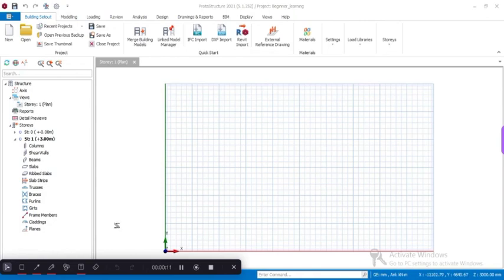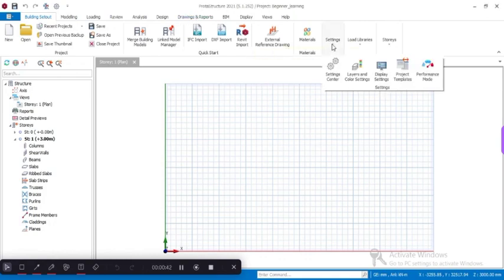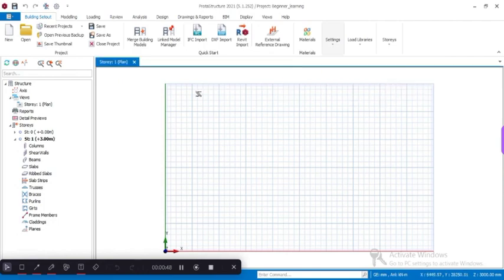So with this now, the grid lines, you will see there are smaller grids inside, smaller boxes. They are 1 meter by 1 meter by default. And then this larger area, the major grid, is colored darker gray. And you can see it's thick and darker. It's 5 meter by 5 meter. And this can be changed by our default setting button. It's all in our design setting, display setting. So this is the display setting, so you can change it there. But we'll get to that aspect.